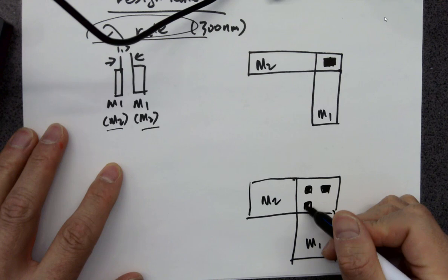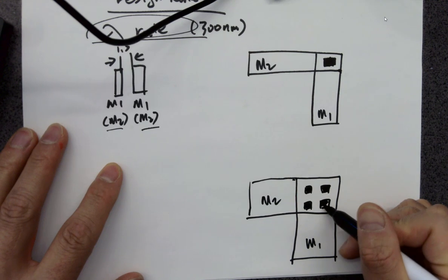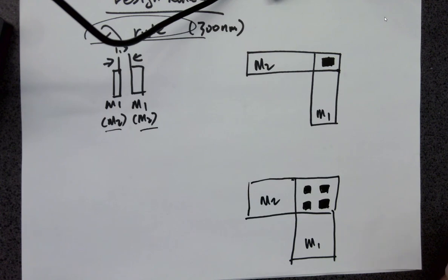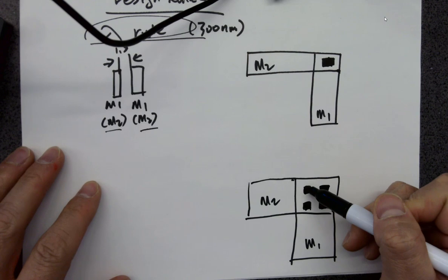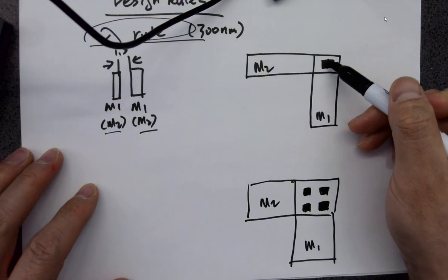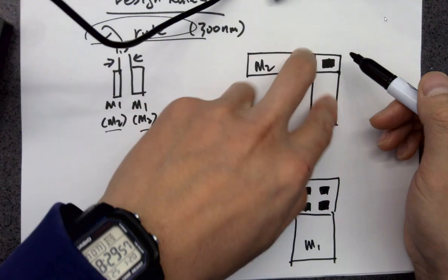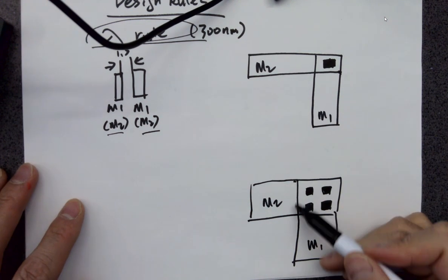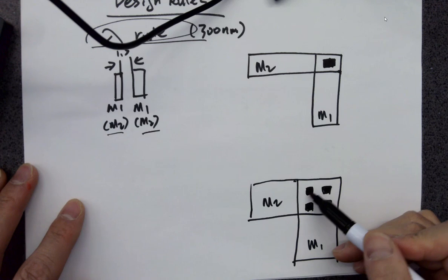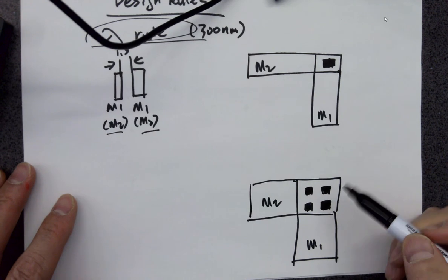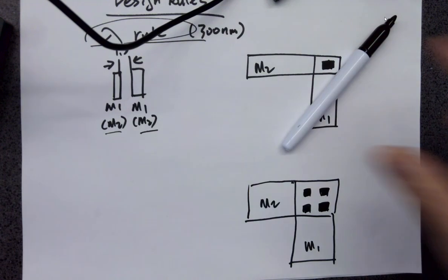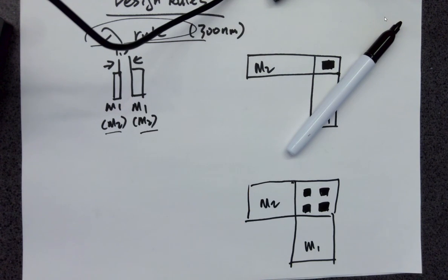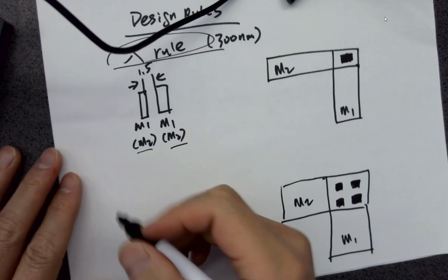And I want to let you guys think about this. Why do they have to do that with the wider wires? For this one, they are not able to because they have limited space in between the two metals, right? So they don't have space for more vias. But now when they have more space for more vias, they would just directly put an array of the same vias inside to try to make the connection. So you can imagine it's basically two metal layers in two different spaces having two poles making the connections. So there are three benefits of doing this.